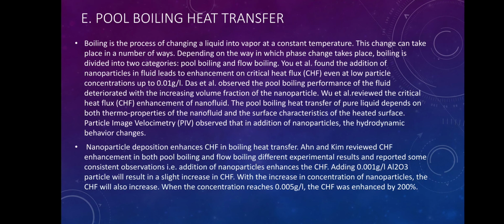Das observed that the pool boiling performance of the fluid deteriorated with increasing volume fraction of the nanoparticle. Wu et al. reviewed that for the critical heat flux enhancement of nanofluids, the pool boiling heat transfer of pure liquid depends on both the thermal properties of the nanofluid and the surface characteristics of the heating surface. Particle image velocimetry observed that with the addition of nanoparticles, the hydrodynamic behavior changes. Nanoparticle deposition enhances CHF in boiling heat transfer.